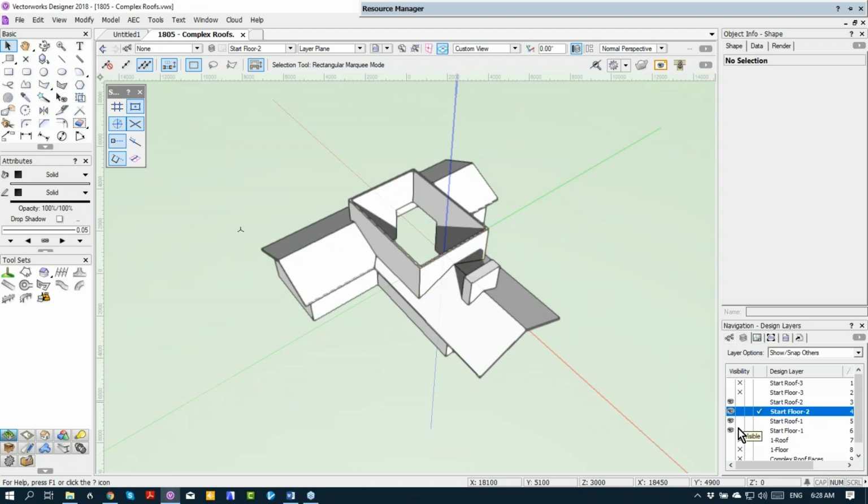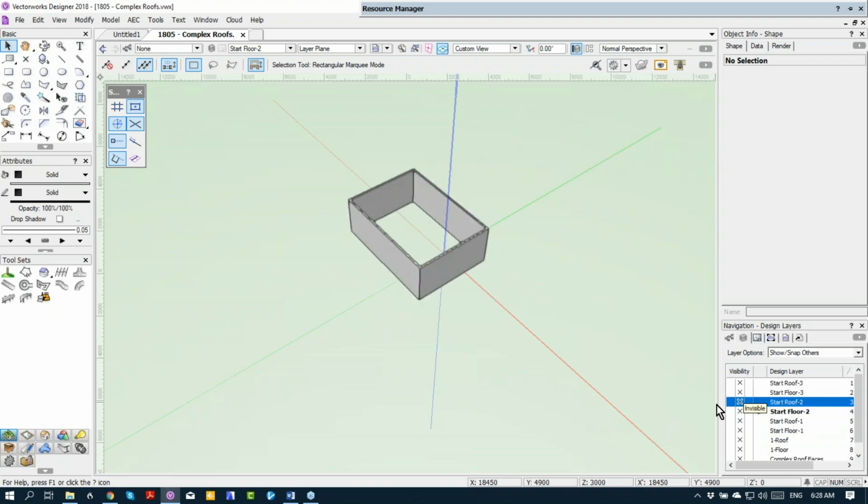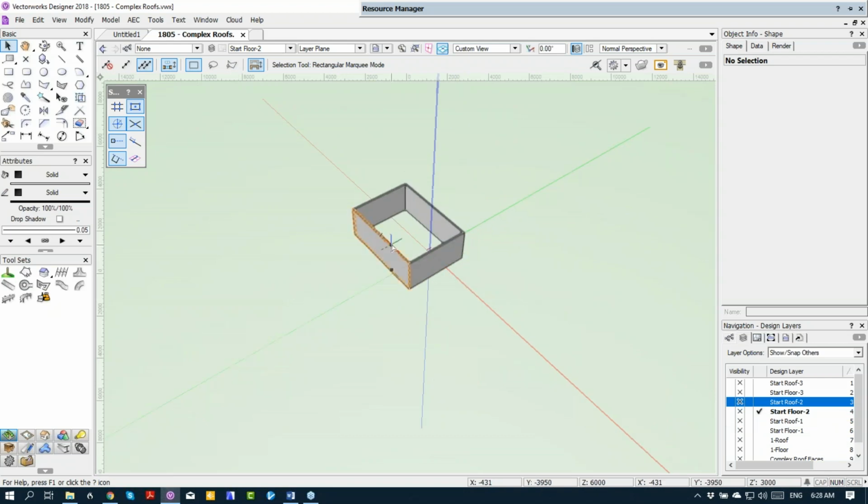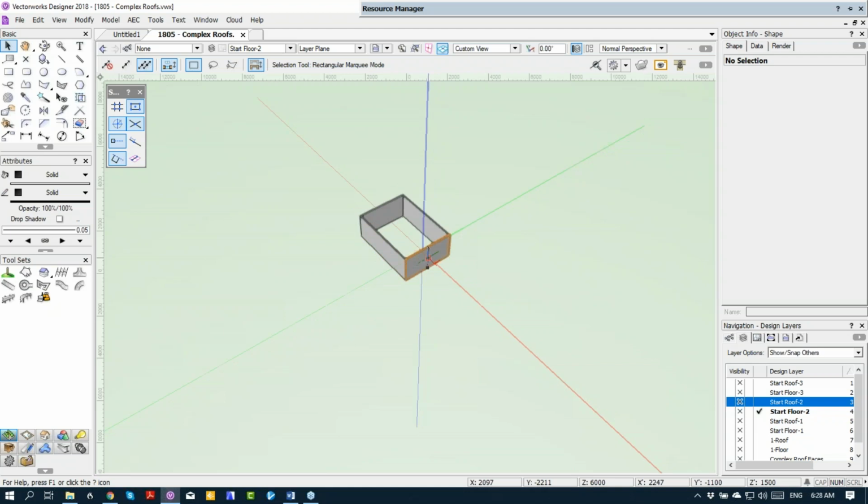So let's move on. So what I'd like to do is look at how do we deal with a more complex issue, like a barn. Yeah, okay, Jake, so it'd be the same as what I said to James. You'll need to make it in two parts. The steeper part is one roof style, and the shallower part of the roof is another roof, and you just have to cut them. But you might also find that using a roof face is the easiest way to do it.